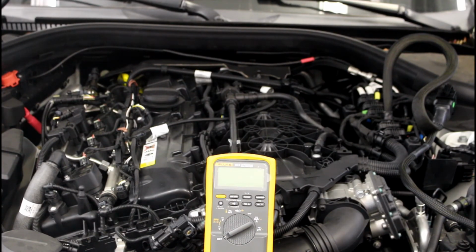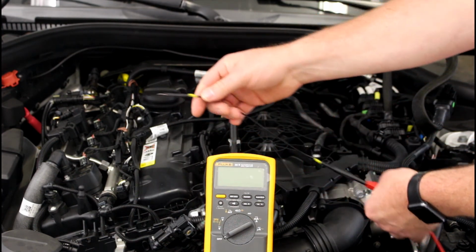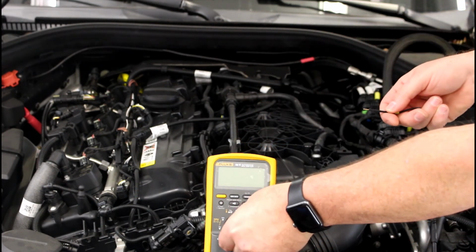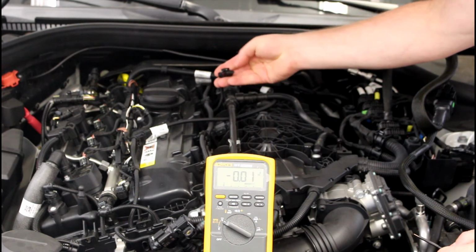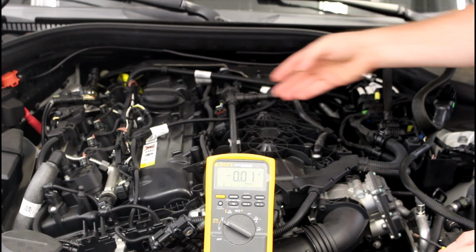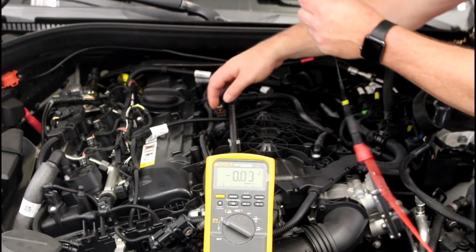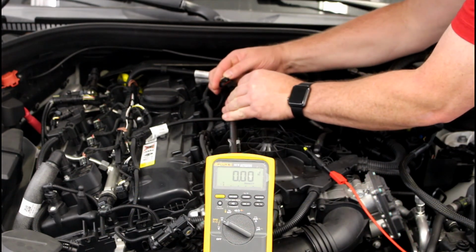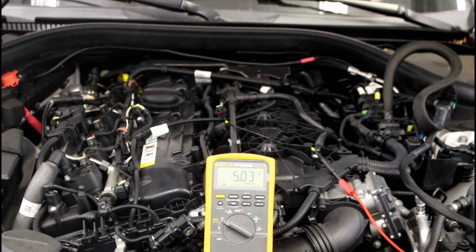Let's check the sensor side now. The way we're going to do this is by looking at terminal number 2 of that B439 connector. Okay, with my ground already on the breakout box, I'm going to use these red long banana clip leads that come with the kit. And using a size number 2 terminal, this is how we will check it. Now mind you, BMW does not back probe. They front probe with a proper size terminal. And that's what we're going to do here. So using the SSP, I'm going to find out which one is number 2 and plug it right in. I should have 5 volts. Sure enough, I do not have an open in my wiring going to the sensor.